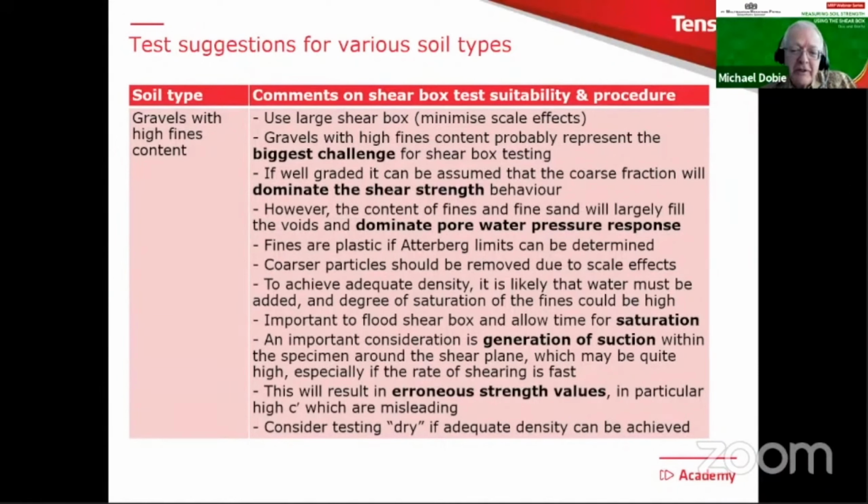But then we get worried about the situation with creation of suction on shearing. I'll show you a little picture of that in a minute. That will happen if you test very quickly. But the problem is with a large shear box, if you go through the full saturation, consolidation, and shearing procedure, then the duration of the test could be extremely long. And to be honest, people would rarely do it. So what do you do?